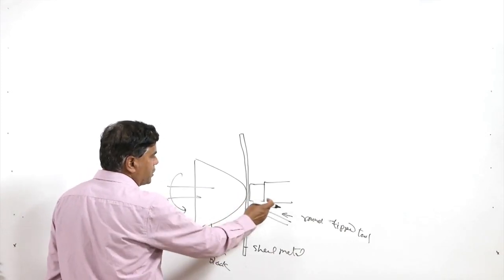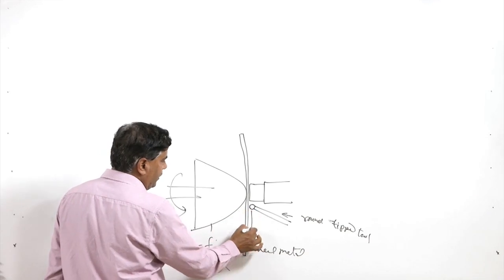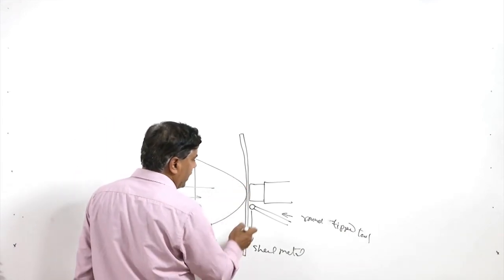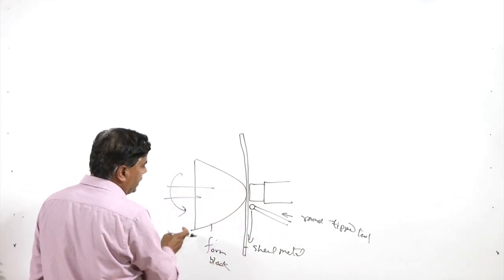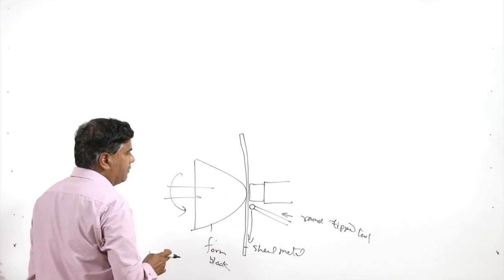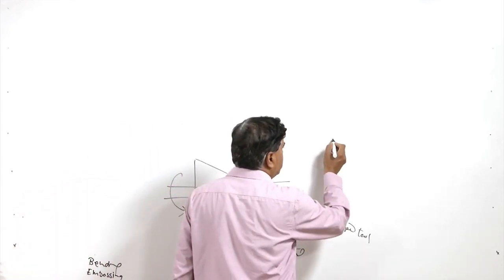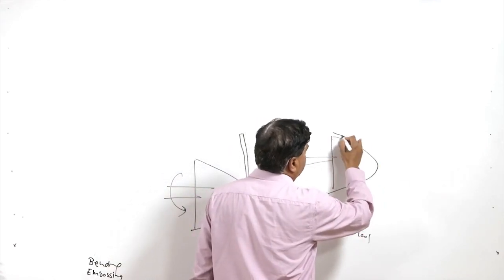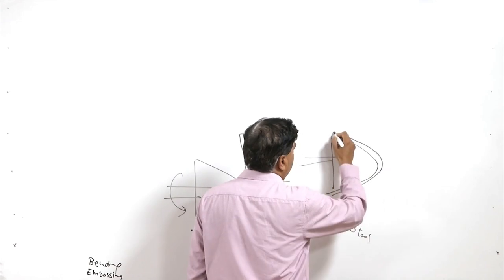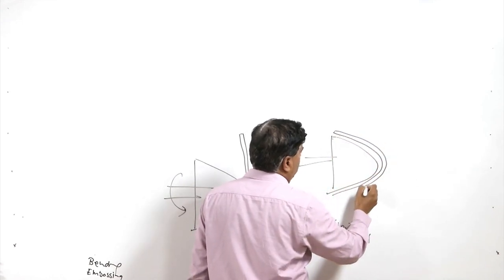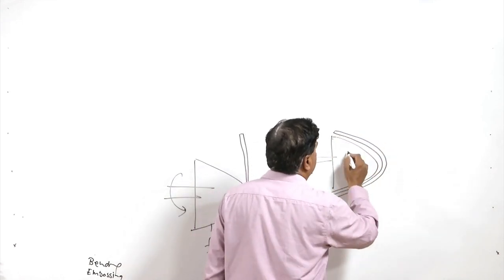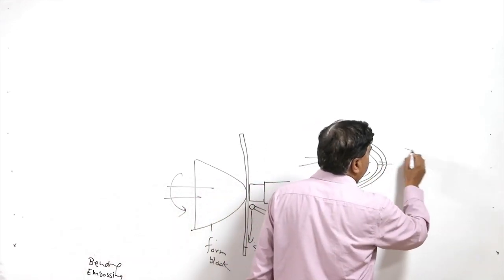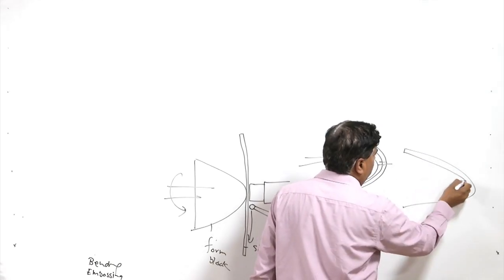As soon as the pressure is applied all along the radial outward direction, the sheet metal takes the shape of the form block. There can be different geometries for the form block as per the requirement, but in this case eventually we will be getting the sheet metal of this shape.